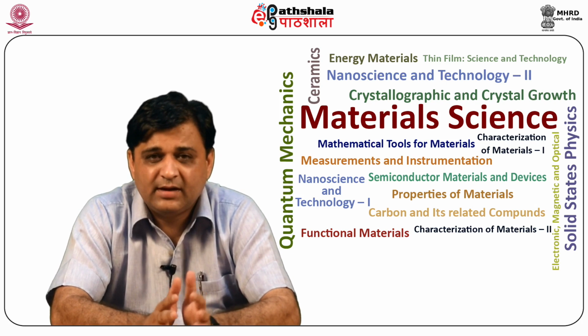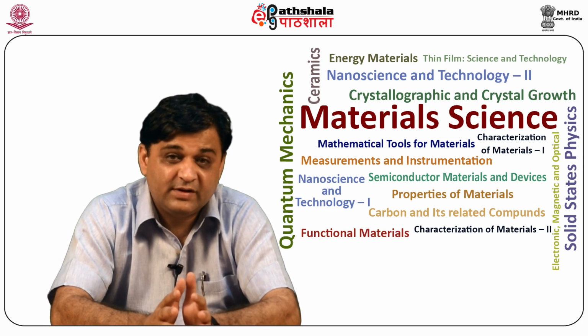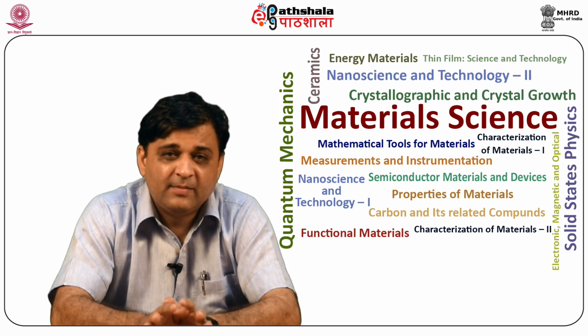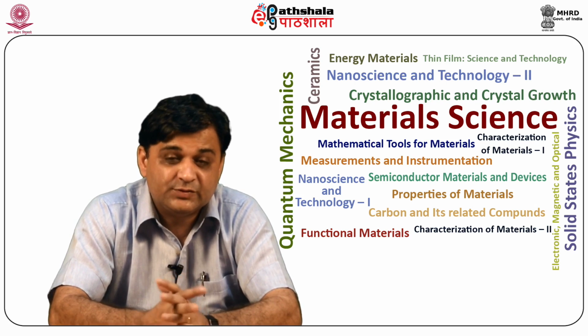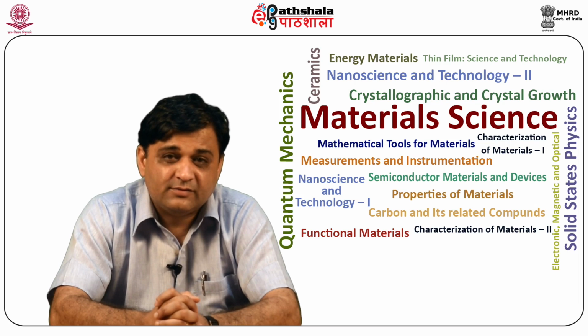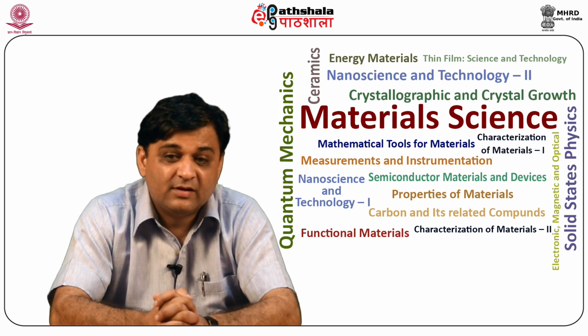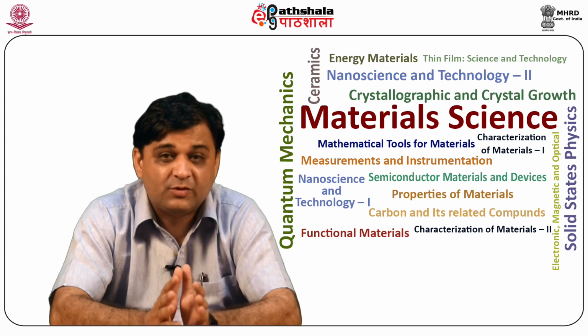And we remember that here we are getting the average information of the surface, and if the surface or interfacial roughnesses are very high, then it can really destroy the reflectivity pattern, and we do not see the oscillations which we used to see. So these are the techniques which can be used to study film thickness. The maximum thickness we can possibly use with the technique is some 1000 angstrom, maybe 2000 angstrom. If the thickness is larger than that, it goes beyond 1000 or 2000 angstrom.